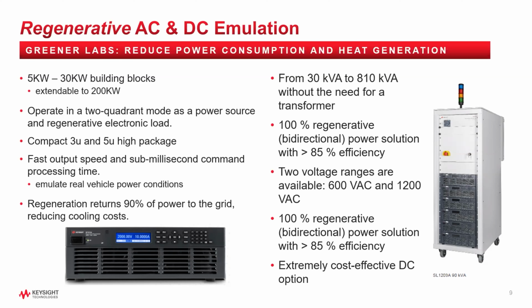but they're regenerative. So we're recovering 90% of the power that isn't wasted, and we're converting it from DC back to very clean 3-phase AC that can be used on the charging side, for example. So this keeps operating costs low, and we're not having to deal with dissipating a lot of heat.